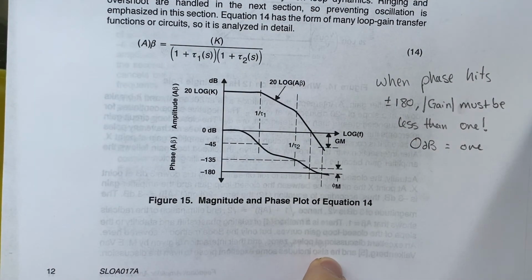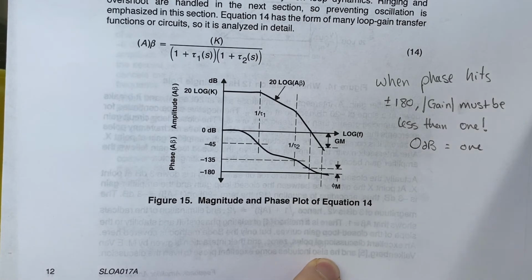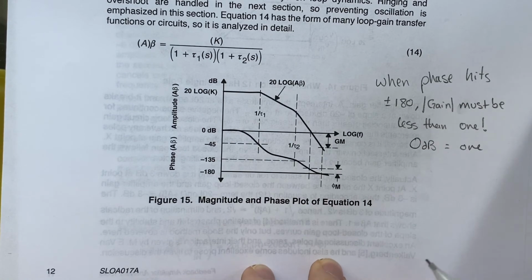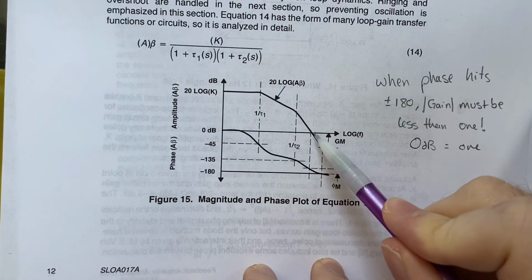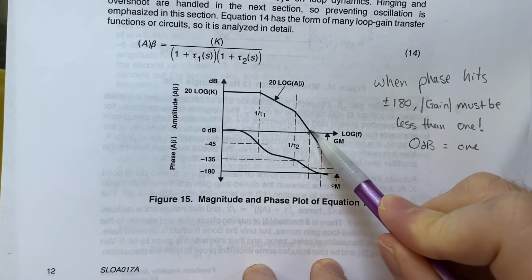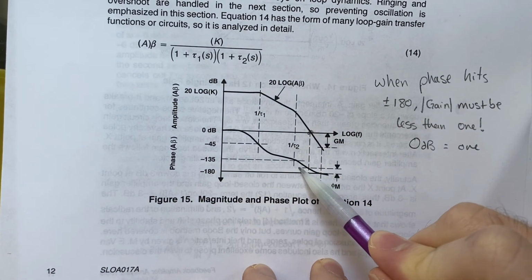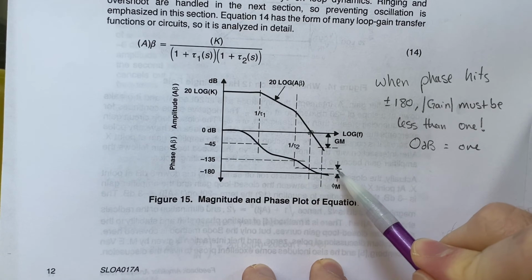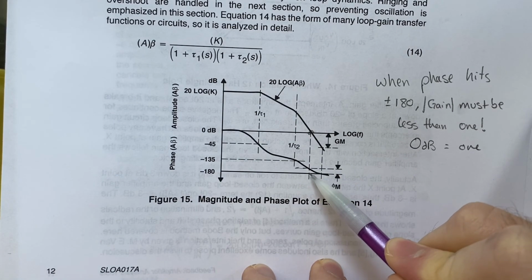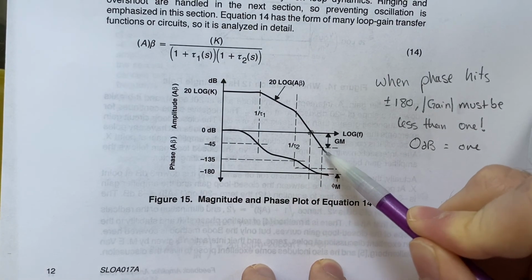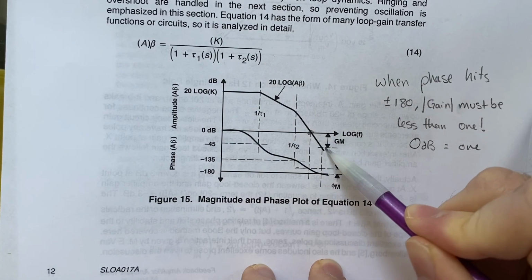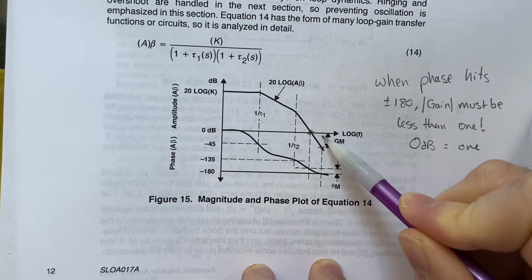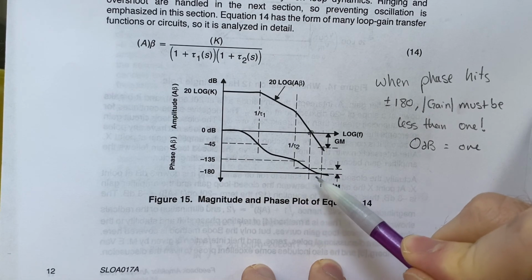And lastly, I'll talk about gain and phase margin, which you'll hear about when talking about stability. Like I said before, when the phase hits 180 or minus 180, you want the gain to be less than 1 so that you don't get instability and your output doesn't go to infinity. So here we see when the gain crosses unity, our phase is not quite at minus 180. So the difference you have until you're out of luck is the phase margin here. And similarly, the gain margin is how much gain you could have had when the phase hits minus 180 or 180.